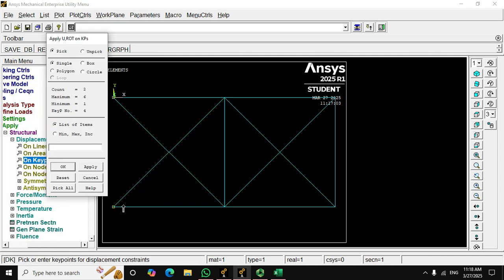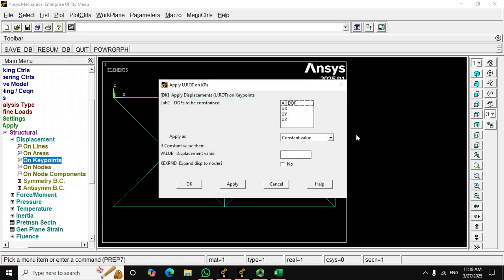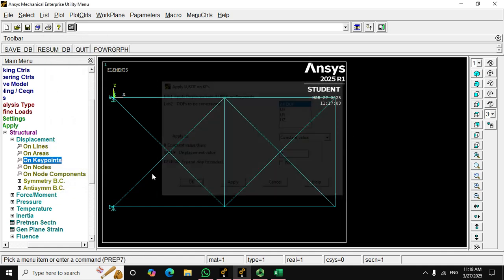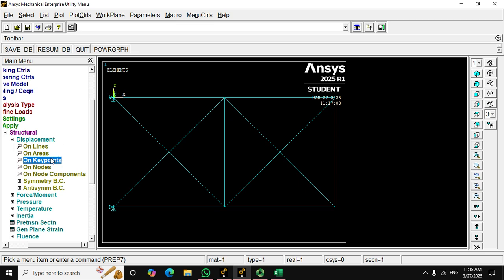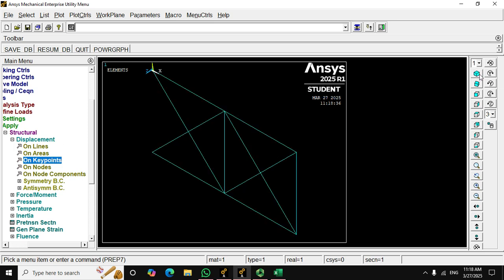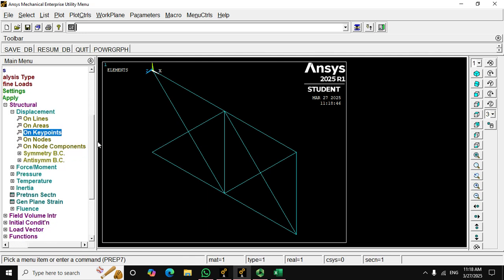So these two guys, I'm gonna zero them, right? Everything zero. And let's look at this, by the way. I want to find frequencies and mode shapes only in plane XY, on plane X and Y, because I just want anything happening in 2D, not the 3D case.